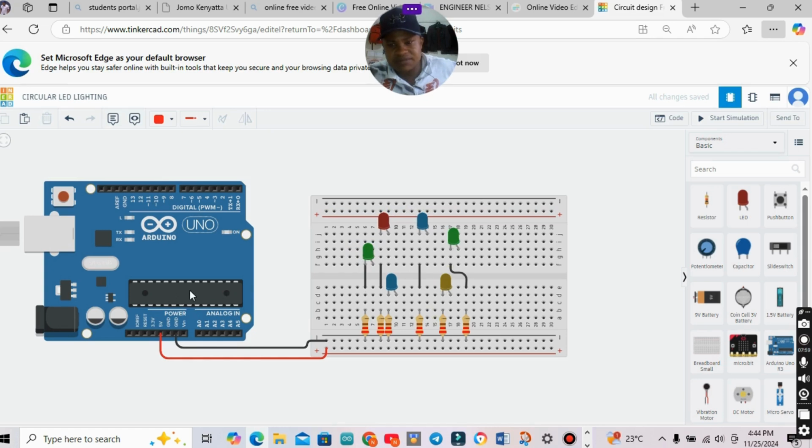So you can proceed to do the connection. Before we proceed, I also added that you can use any of these digital pins from pin 2 all the way to pin 13. You can use any of them, with the exclusion of the first 2 and the last 3. Those exclusions are preserved for special applications, especially in scenarios where we are involving serial communication. So we can now start our connection.